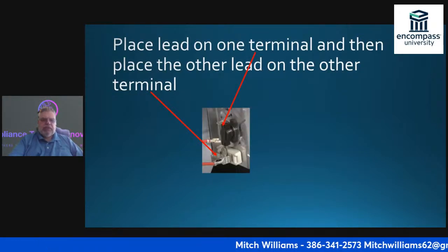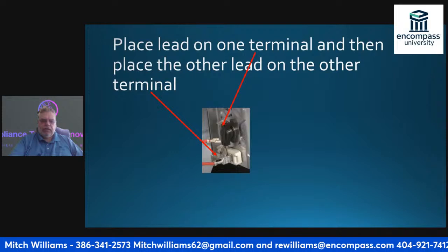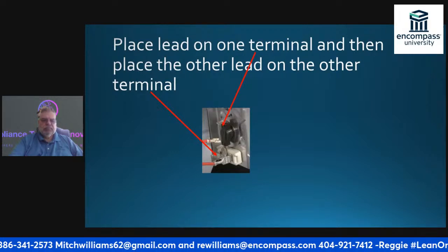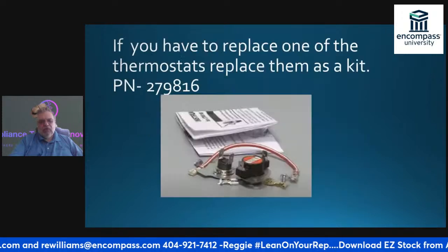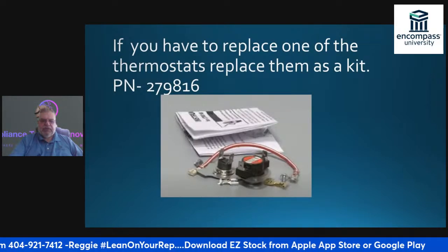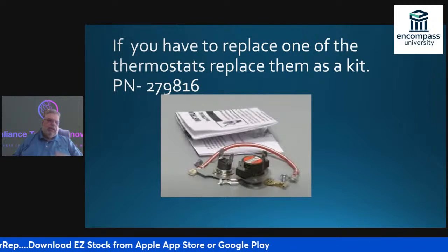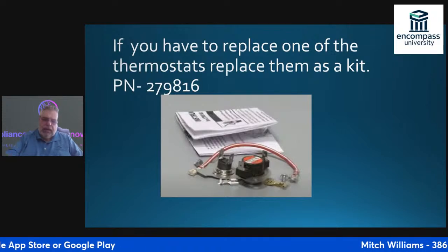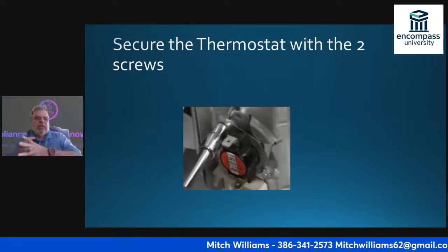I'm going to take and place a lead on the terminal and then place the other lead on the other terminal. If you receive a tone, the fuse is good. We've already been through this. If you need to replace one of the thermostats or this thermal fuse, I can do that as a kit. That's the part number for a Whirlpool thermal fuse and your other part. It comes all in one big kit.